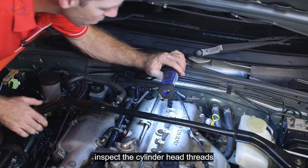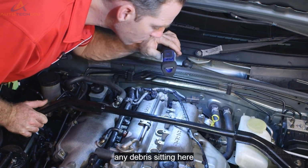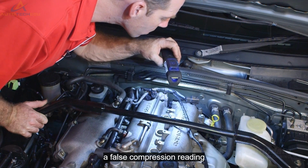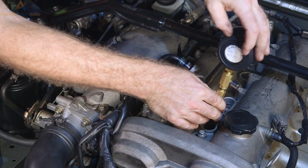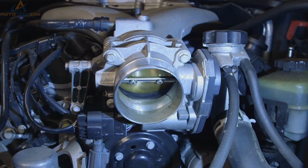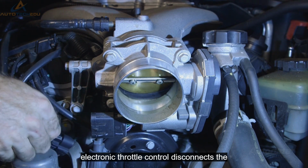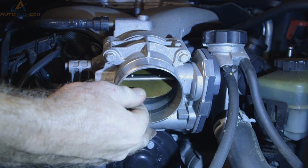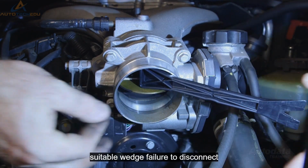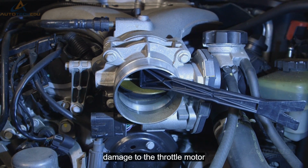Inspect the cylinder head threads and the plug seat closely. Any debris sitting here will not allow the gauge to seal correctly and cause a false compression reading. Connect the compression tester. If the vehicle has electronic throttle control, disconnect the throttle valve harness connector and prop the butterfly in the open position with a suitable wedge. Failure to disconnect the harness may cause damage to the throttle motor or valve.